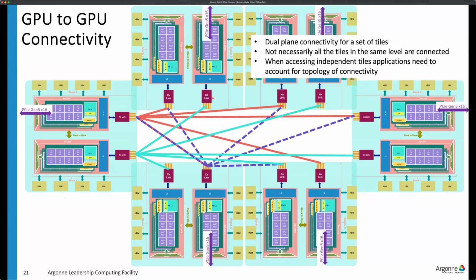In this slide deck, I try to highlight how that is in an illustrative manner, right? If you look at the red links of stack 0 of GPU 0, you will see it connected to stack 1 because that's the closer point next to it. Similarly, stack 1 of this GPU. But if you go to this one, it's more of the stack 0. Therefore, when you go for the dual stack placements and application optimizations, and if the application is going to utilize the Exascale links to do the data movement explicitly, then what they need to do is account for the topological differences.